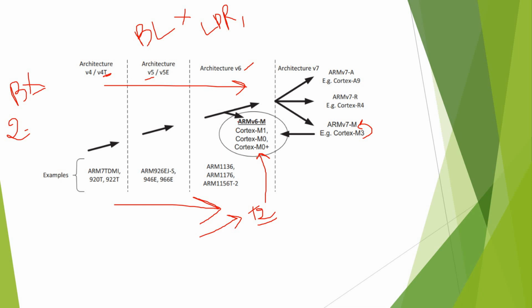In the mainstream ARMv6-M, we have two processor implementations, Cortex-M1 and Cortex-M0, and there the focus was to have full support of 16-bit. So ARM wanted to test the full capability of using 16-bit without the need for real 32-bit. Even though a couple of instructions were left as 32-bit on this processor, like BX and BLX, they are executed as 16-bit instructions. This allowed ARM to improve the code density and the code size by using full 16-bit instruction-based assembly code.